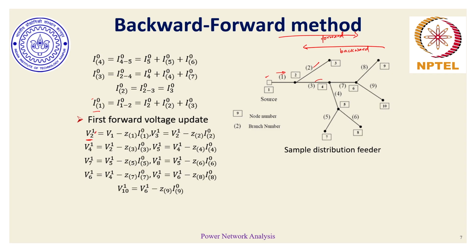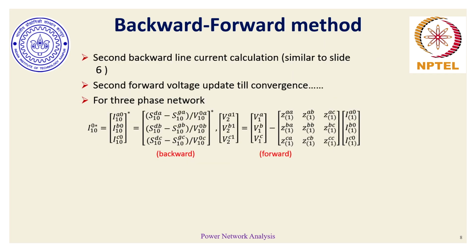So that basically 0.5 step in the recursion is because of the backward phase and 0.5 is because of the forward phase. And using these same currents, depending on the impedances present in these branches, we can find the corresponding voltages and do the same step till we reach the far end voltage nodes. This sort of a process would continue till convergence happens. The convergence might happen when voltages don't change, currents don't change, or the power valuations don't change.